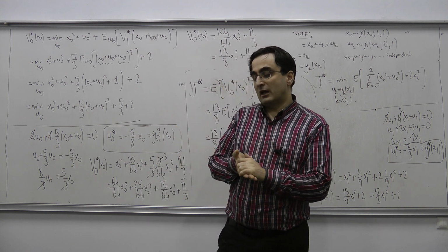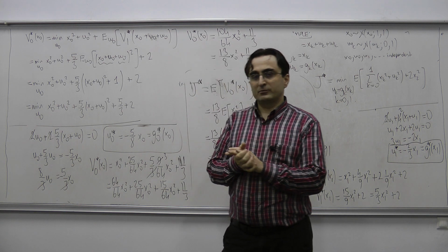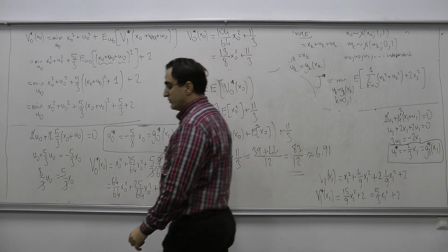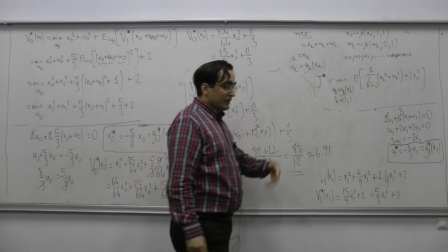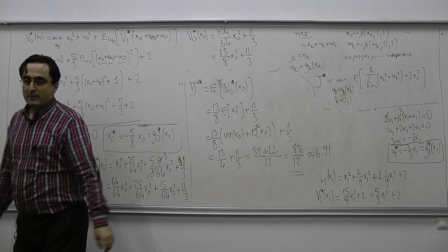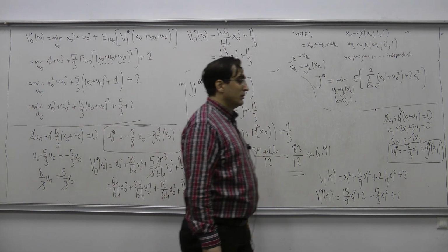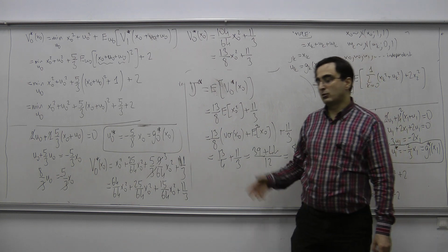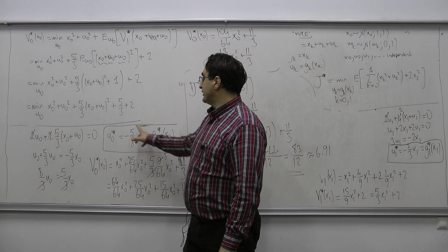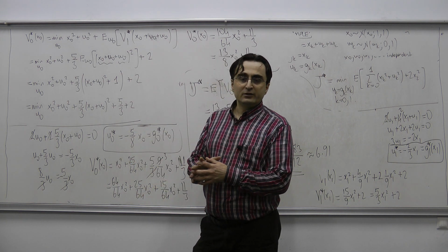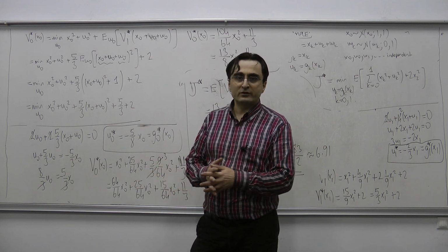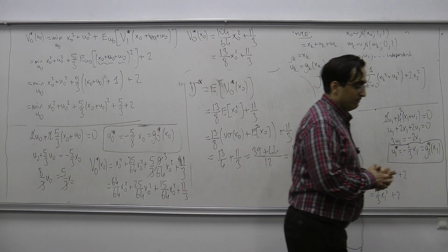We're going to try to generalize the results on these systems in the case of multidimensional inputs and multidimensional states. These were just scalar examples with scalar inputs, and we're going to see that even if the system has multiple states and even if the system has multiple inputs, for linear Gaussian systems, the optimal inputs would always turn out to be a linear feedback, like this, and the optimal costs would always turn out to be quadratic if we have a quadratic cost function. Okay?